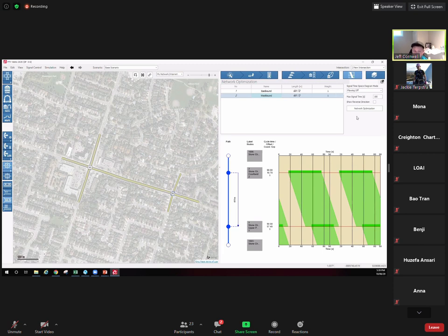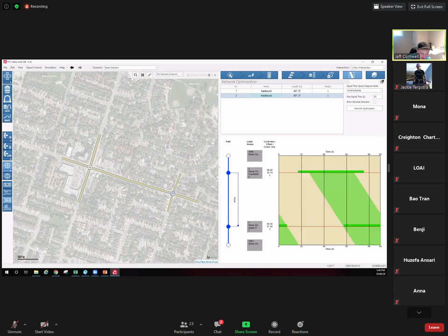But what's important here is on the top right. I like watching as bands, so you can change it from this floating off. My preference is imperial bands. And this shows the total signal time here. So if my cycle length is 90 seconds, I really only need to look at 90 seconds. So by default, it's showing double. But if I typed in 90 here, now it just shows one group of bands.